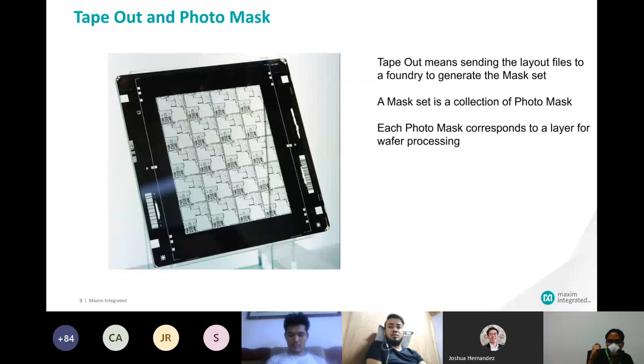So you can select a mask set that is metal mask, which is really the interconnect, which we can see later on, which is the interconnect between those devices on a planar IC process, and you can change the connection, and thus saving the full mask set.